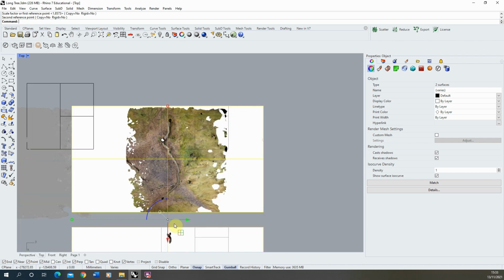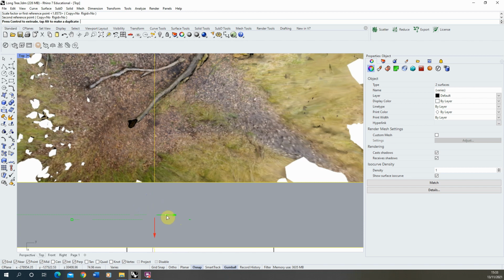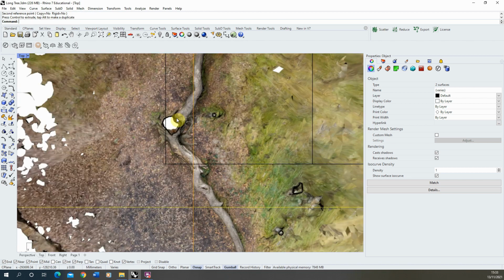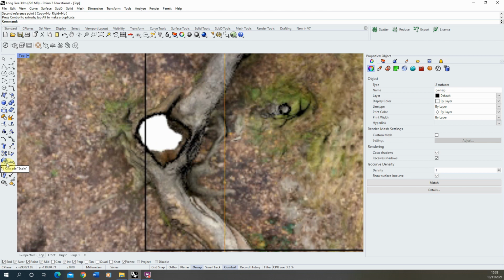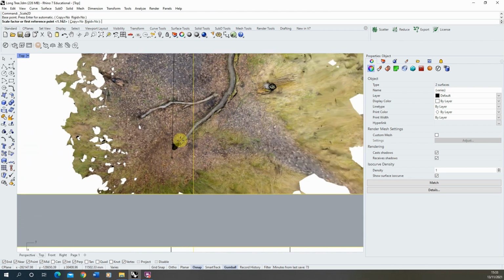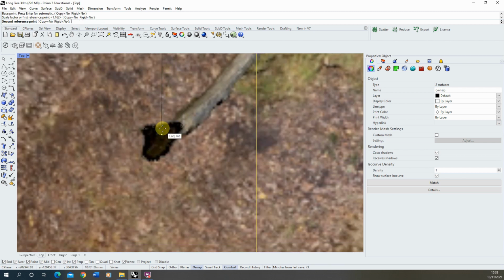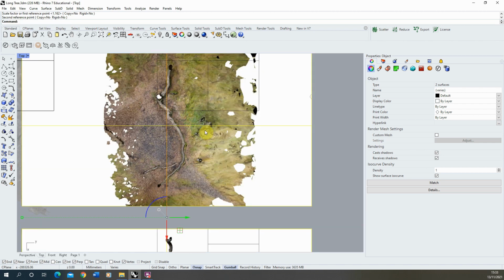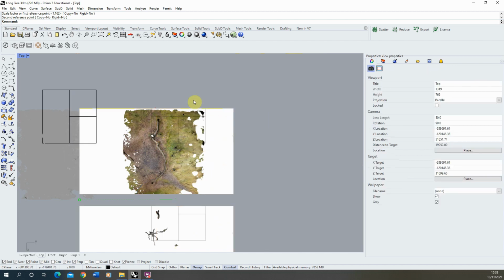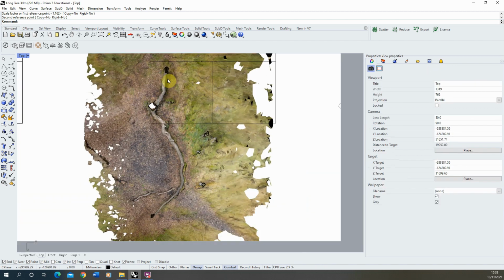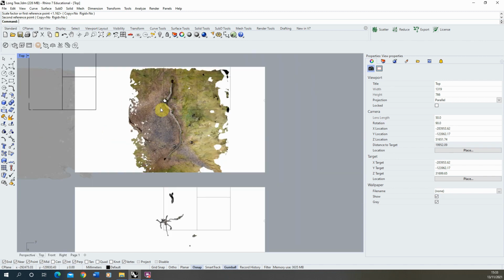and just scale this accordingly to match the plan. And as before, you can take a bit of time to get this exact. Sometimes it's easier if you sort of scale it from a point on one side, scale it from here in relation to a point quite far away here, and so the accuracy lines up, and there you can see my lines are now in place. So now we've lined those up, much like the section, I just need to draw out these pieces in elevation to give my plan a bit more sense of depth and to show those extra objects in. So I'm going to pause the video and just trace around those elements here.